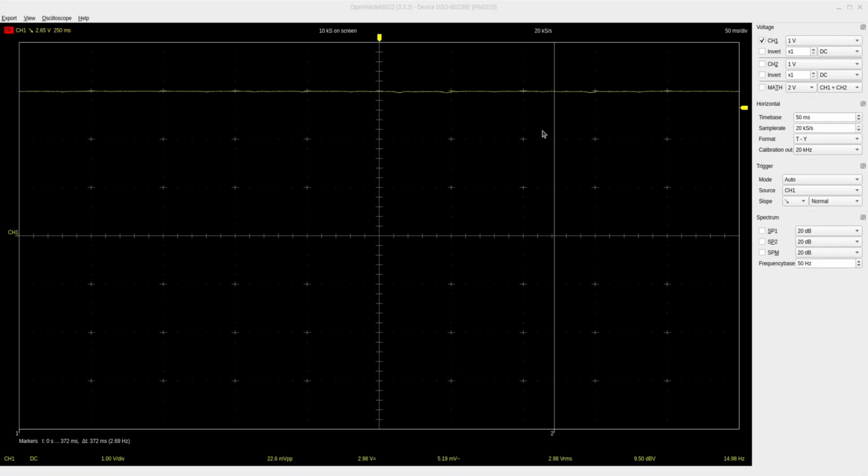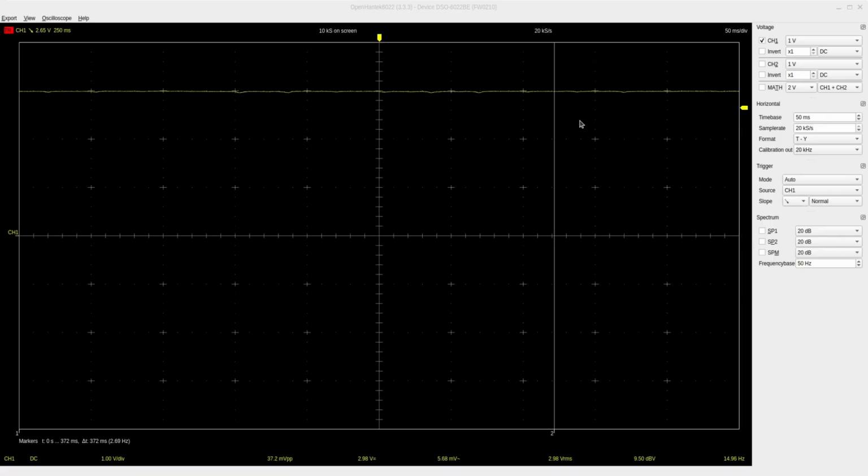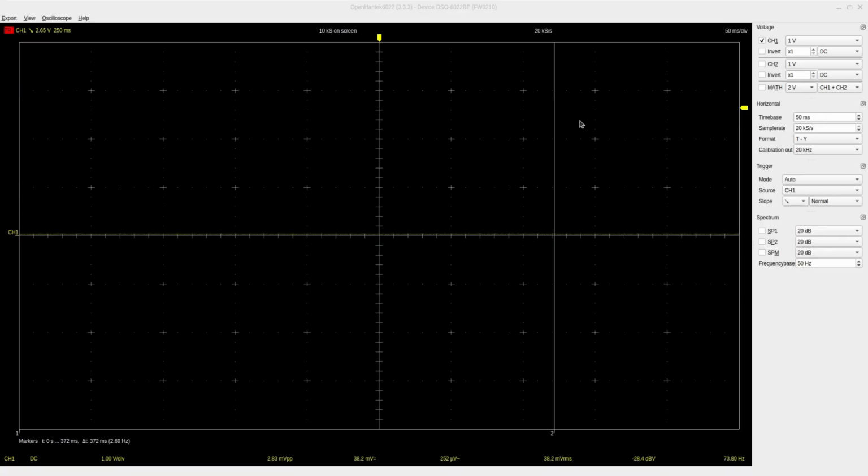So now we're ready to interpret this button signal a little bit closer. Let's take a look at it on the scope. We're looking at the microcontroller input that the button is connected to, and at rest we can see it's sitting at about 3 volts. Yeah, I know, I see a little bit of noise on that line as well. I'm just going to blame it on the breadboards. And when I press the button, it drops right down to almost 0, which is precisely what we'd expect.